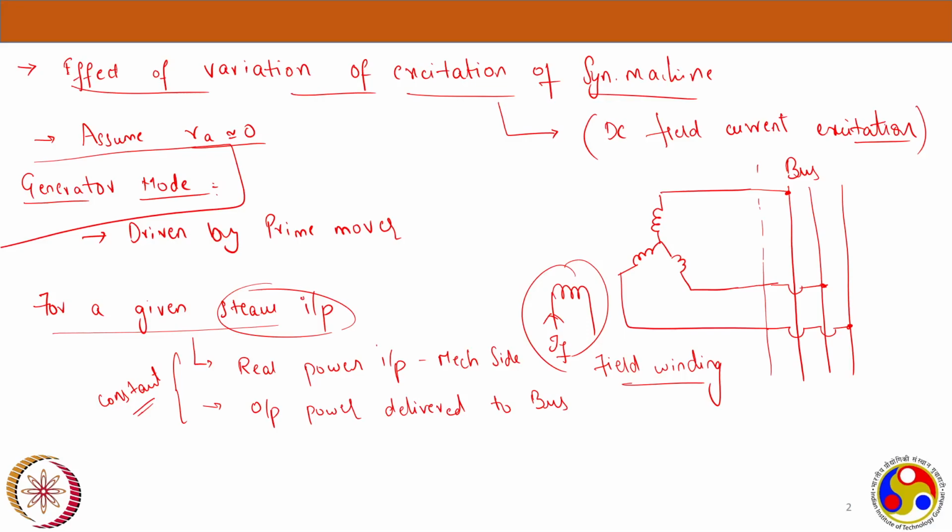The main motive of today's discussion is that by controlling the excitation of the rotor, by controlling the DC current flowing through the rotor, I can make my synchronous machine operate as a leading power factor delivering machine or a lagging power factor delivering machine, and that's very useful with respect to the practical application in any industry or any power requirement based station.